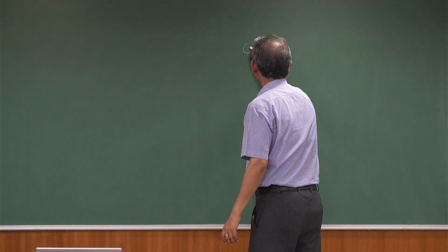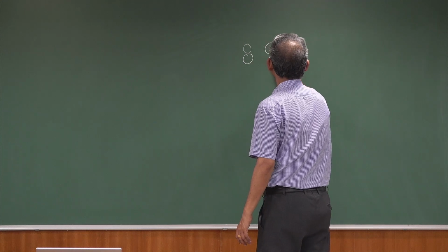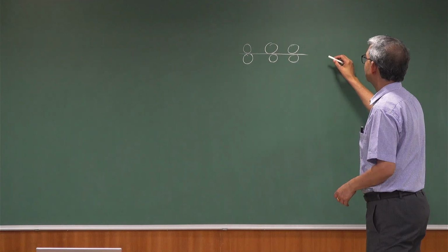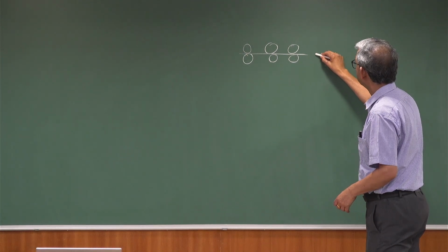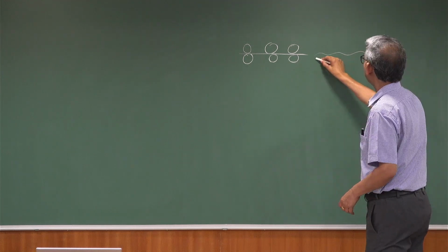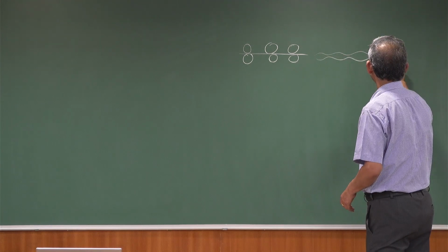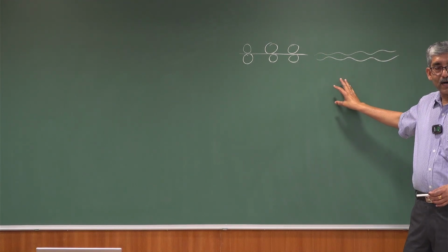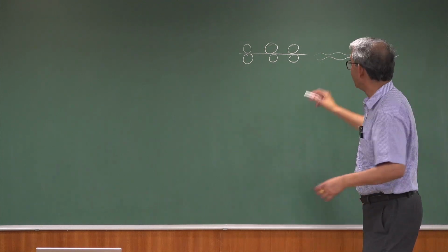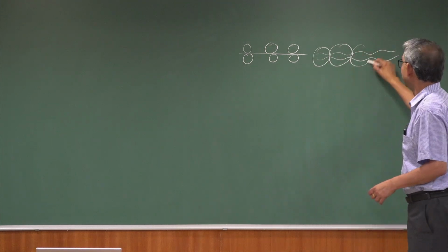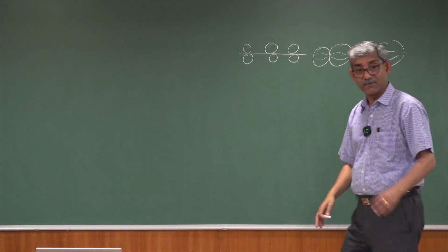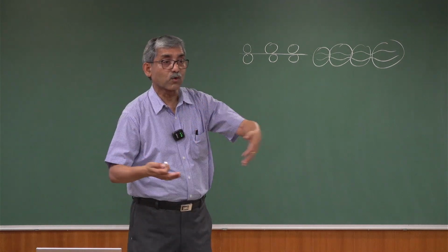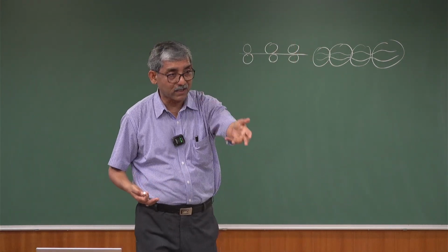In the ring frame, we are getting yarn which has thick and thin places. These thick and thin places, if they are random, it's one thing, but if they are periodic, this will be due to some roller defect or some pinion defect.